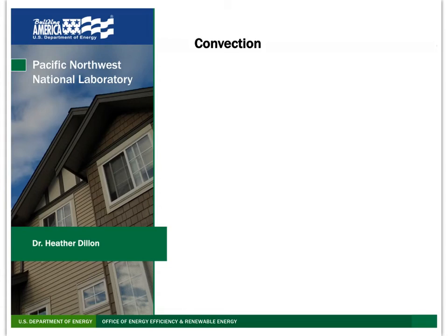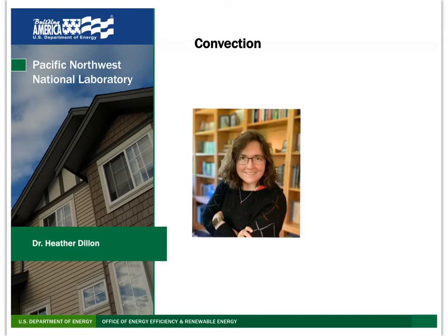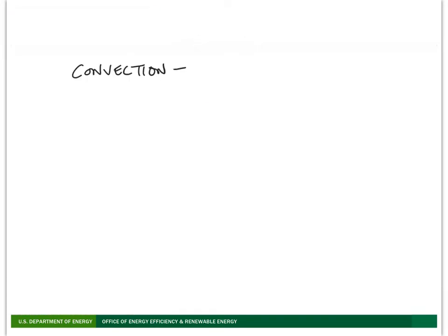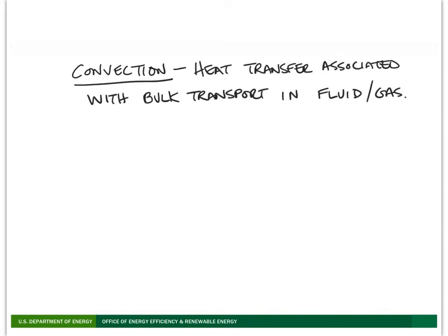In this video, I'd like to give you an overview of convection and a little bit of additional detail about how convection actually operates and some of the calculations that you can do for convection inside a building. Convection is a type of heat transfer associated with the bulk transport of particles in a gas or a liquid.